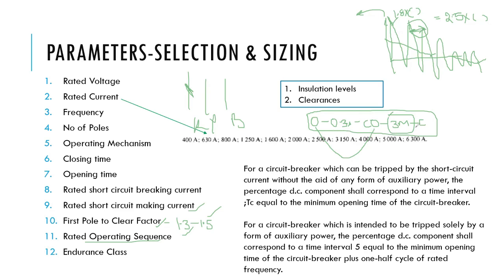So why do I require this? Generally, this is the condition you can see in the auto-reclosure function. As I said, we now have the three phases R, Y, B. Suppose the R phase got a fault, a tree branch hit the R phase, and the fault happened. It's a transient fault.